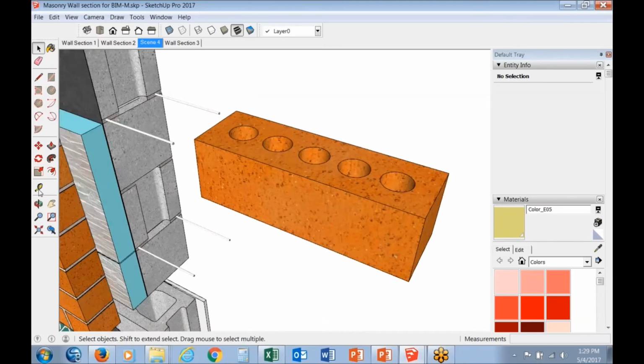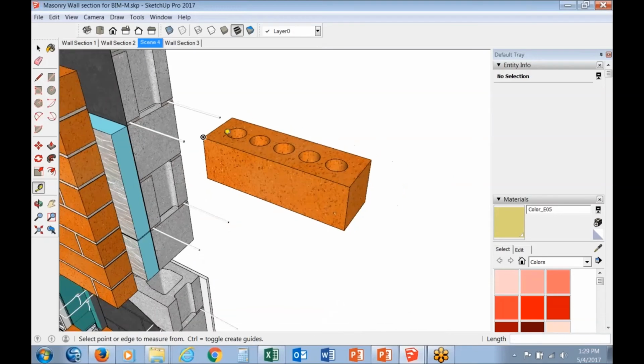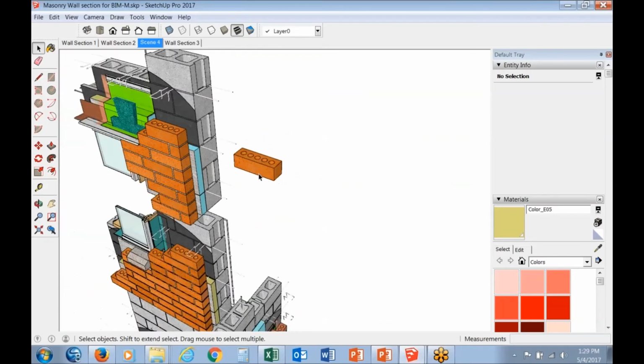Well, is it perfect? I always verify. You click on the tape measure, because many times you don't know who built these models, if they're to scale or not. But a quick dimensional check will confirm that whoever made that model knew what they were doing. And you can save this as an SKP file and manipulate it and use it.